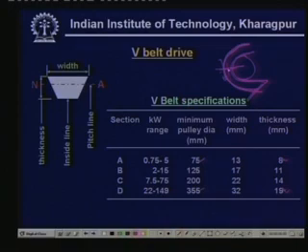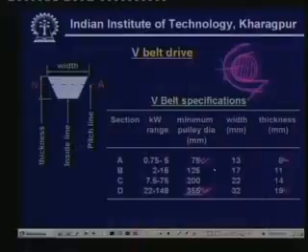One has to look for what should be the minimum pulley diameter. This pulley becomes a guiding factor, because an A section belt has a lesser thickness, its minimum pulley diameter is 75, and in the same logic the D can go as high as 350 mm pulley diameter. So, in this particular case, one is warned that use of minimum pulley diameter is always recommended while going for V belt drive designs.